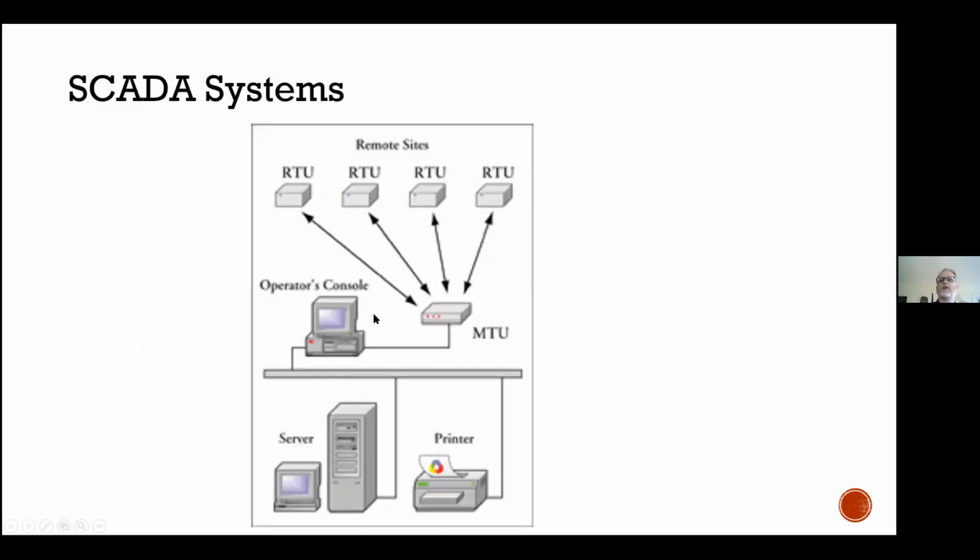One of the issues too is that now they're all web-based, they used to be hardwired dedicated systems. There have been a couple of situations in the news where, at a small water system in Florida, someone hacked the SCADA system and actually added chemicals into the water supply when they shouldn't have. The operator got the alarm that, I think it was sodium hydroxide, was too high and was able to shut it down. So yeah, there are benefits from it, but also risks. But the ability of the technology now to tell an operator what's happening at a pump station or at a reservoir is amazing, because of course it saves the operator from having to go to the site to diagnose the problem.